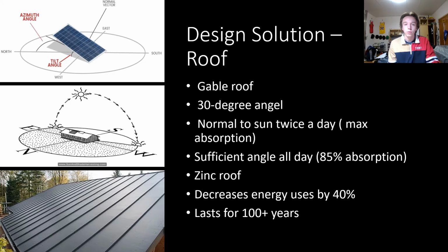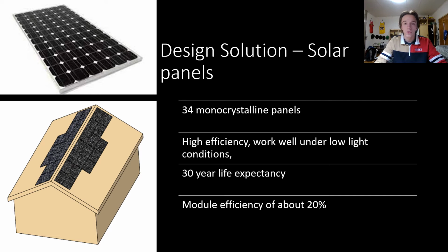The design will consist of 34 monocrystalline panels, which have a life expectancy of up to 35 years, and will have a module efficiency of about 20%. They have a high efficiency compared to other types of panels, and its optimal performance is during high heat and low light.